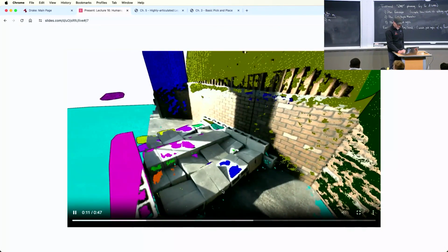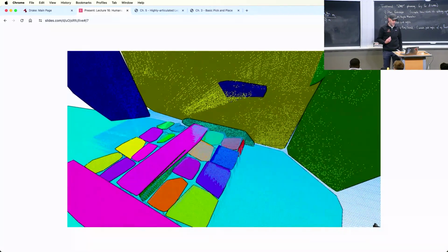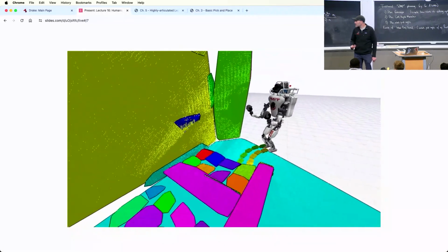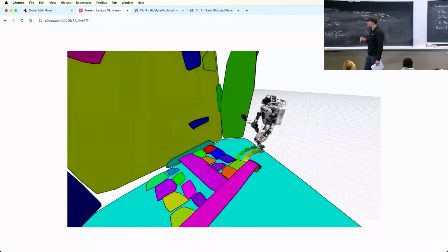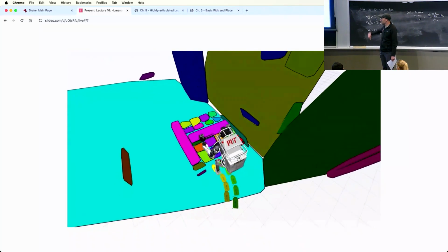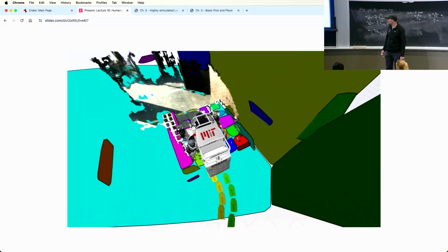Okay, we would identify patches in the terrain that seemed to have similar normals. Okay, we would segment the terrain into places you could potentially step, right? And then we had this footstep planner that if you watch, it's just drawing its planned feet positions. Okay, and then we have the center of mass trajectory above it, and this will go again. More interesting when it gets on the terrain.